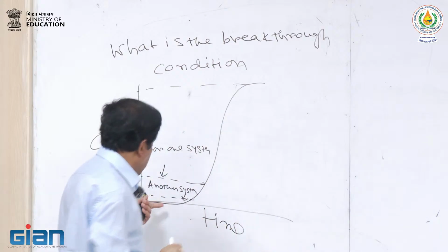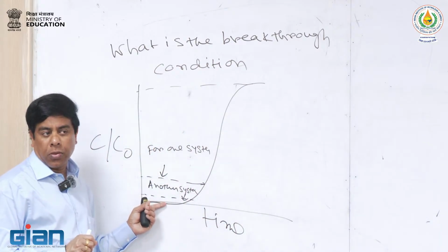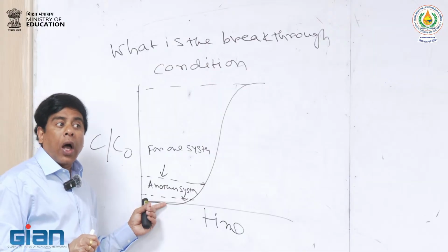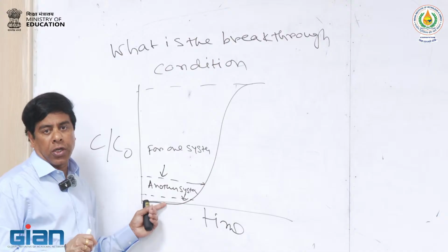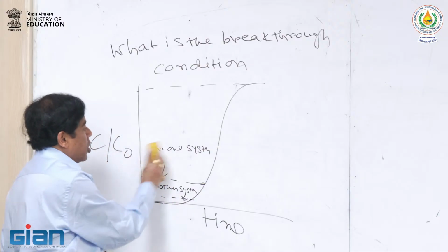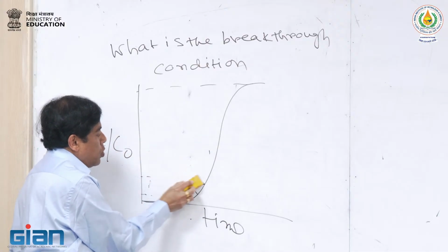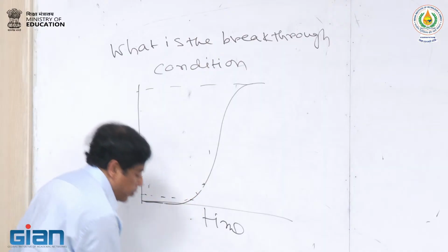But when you are doing the CO2 capture processes, it's different. Because if you are targeting 90% capture or 95% capture, remember, during this time, you have 100% capture. So you need a time-average 90% as the breakthrough.